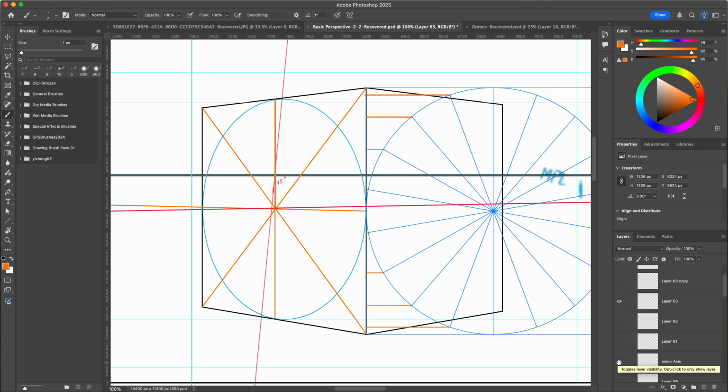All right, we no longer need this face, but I will say this before I click it off. This ellipse template here that I've got, the radial, is that if you had it converging upwards or downwards rather than like we do here to the left, you would maybe want to put your template with your radial on the bottom or the top rather than the side. In this case, it works fine. So whatever edge tends to be working parallel to your picture plane, that's where you would want to flush it up against. Obviously, I don't want to flush it against this unless I'm using the measuring points, and that's just going to give us an extra step. So I didn't do that.